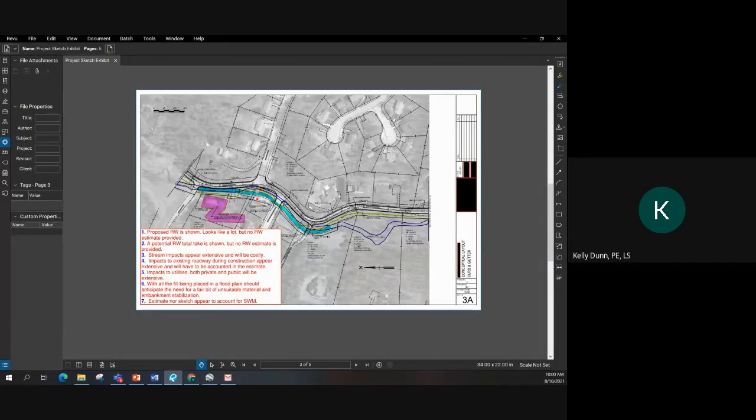From a geotechnical viewpoint, floodplains are usually full of organic material, which is not a great material on which to place structural fill, and thus extensive geotechnical studies may be needed, along with the need to mitigate unsuitable soils via undercuts and embankment stabilization. The PE geotechnical estimate only shows $29,000. Once again, this would be another cost that I believe needs a closer look.